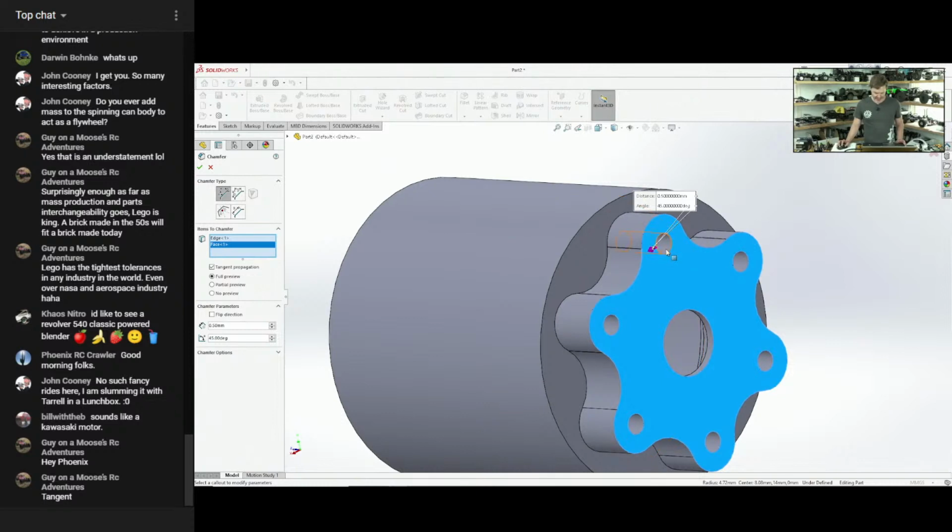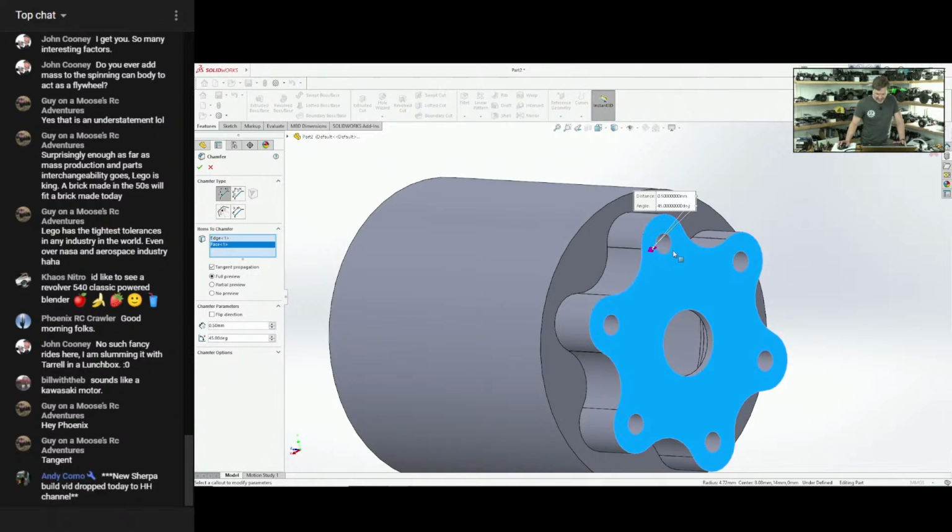And what that is going to give us is both chamfers on the holes, which we always need to make sure that it is really easy to start your threads, and also for the threading operation when they're actually making these in the CNC. If you don't have a chamfer on the edge of these holes, as a machinist, I would hate you as a designer. And I may actually add them myself.